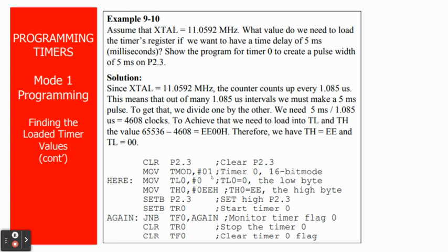So that means we want to use timer 0 mode 1, timer 1 mode 0, as we practice in part 1 of this tutorial series. So again, it's not true that we can only use timer 0 here, mode 1, because we can also use timer 1, mode 0. Now again, mode 1 will be 16-bit mode.